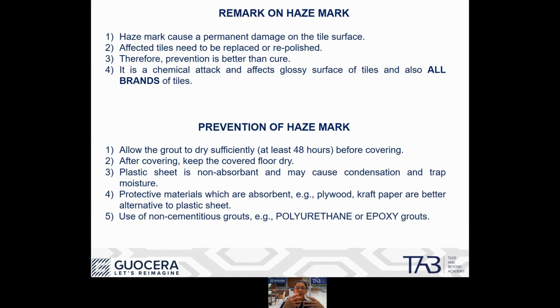Of course, when I say this, I get questions, oh, these are more expensive materials. Definitely they're more expensive. But since we now know the cause is water and also the calcium oxide, the cheapest way would be to keep the floor as dry as possible. And there have been a lot of job sites saying, oh, we can't, because we cannot control the water coming in.